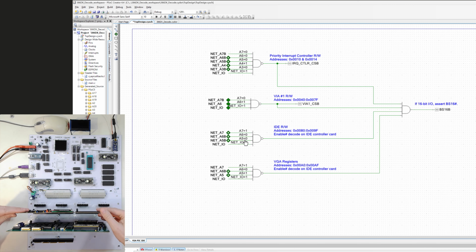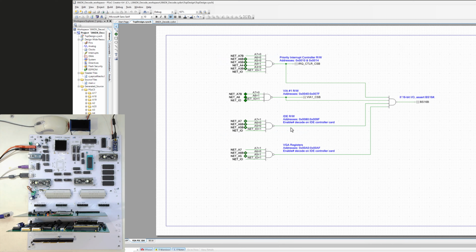Now, ideally, I would change this card a little bit. Let me get this back in here. I'm using those 3 jumpers to help me set this 1, 0, 0 here. And if that is the case, then I know it's enabled. And again, the logic to enable it is on the card itself. I'm just having to make sure I use unique addresses here that don't step on each other as far as these bit patterns. And as I've mentioned before, I should technically put in A8 on up and make sure those are all zeros to make sure I'm not, for example, using a higher address.